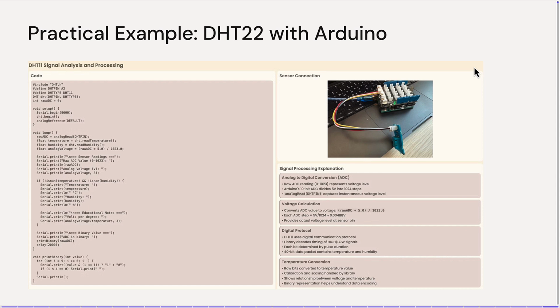We will take it from this pin. And then using the conversion, this is the resolution of the ADC, and multiplied by 5, it's 5 volts. And here we will have a certain voltage. And you will see how the voltage will be impacted by the value of the humidity and the temperature. And of course, all the magic is done in this library, DHT.h. It's the library that will take these raw values and will convert them according to the physical equations that I have introduced in order to get the final temperature and the final humidity.